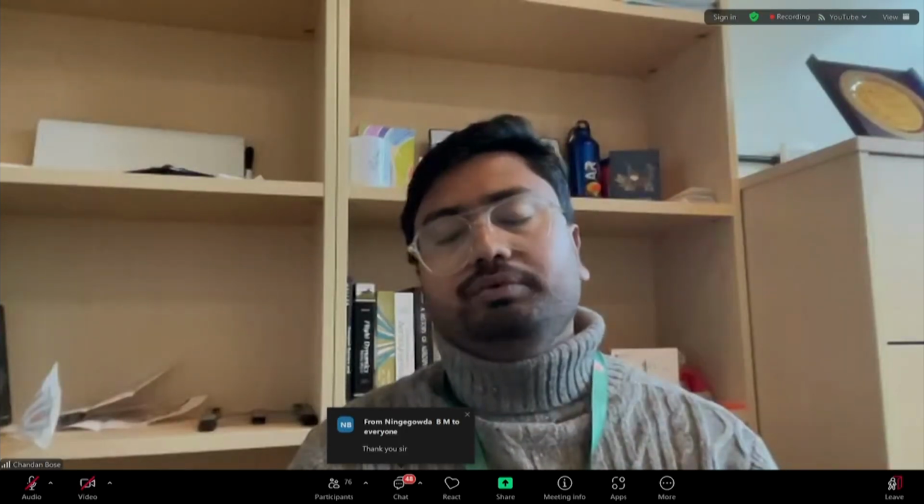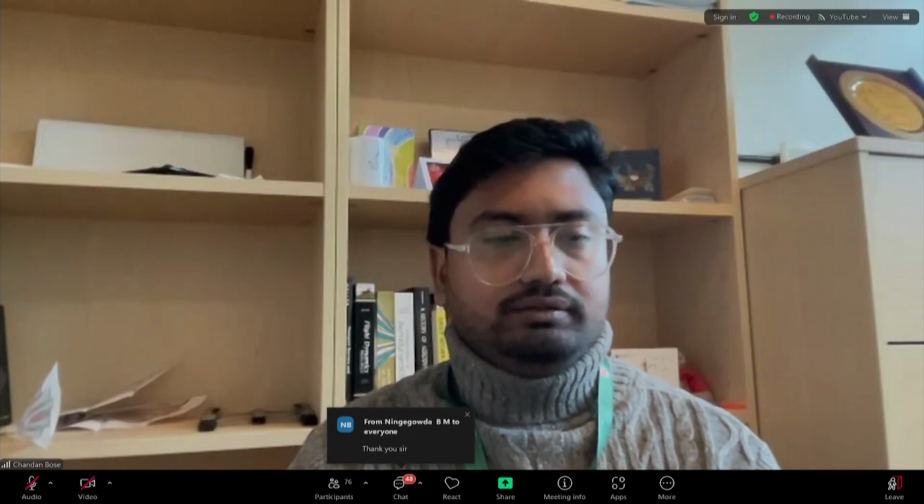So I see there are some more questions in the chat. Which dynamic mesh method is useful to solve boiling flows or combustion? Again, as I said, any of these dynamic mesh methods can be implemented depending on what you want to capture. I think adaptive mesh refinement is a very popular approach for combustion systems, because if you want to capture, for example, flames or other things, you can set the quantity of interest and use adaptive mesh refinement.